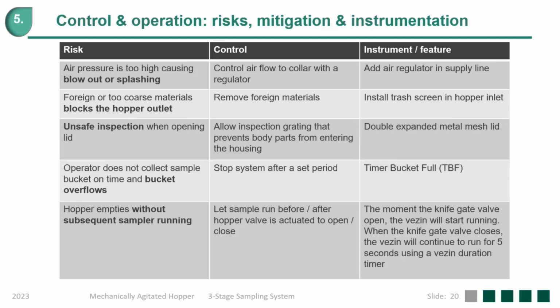The other risk is when the operator does not collect the sample bucket on time and the bucket overflows. The control is to stop the system after a set period. That can be done by installing a bucket full timer in the control panel.